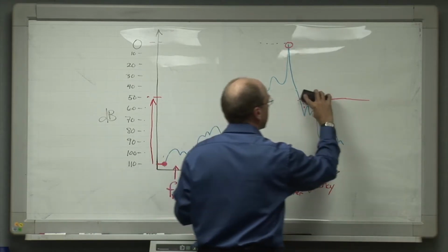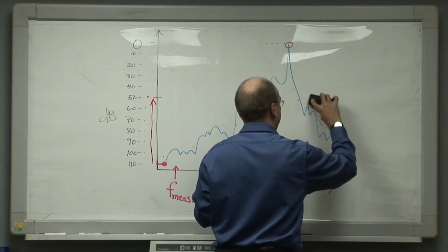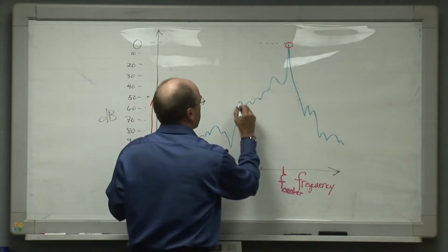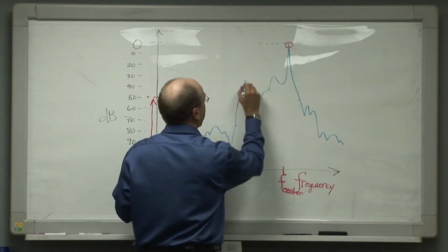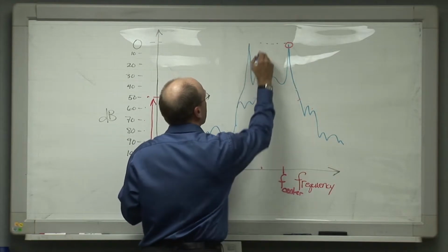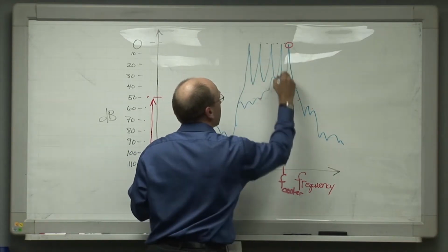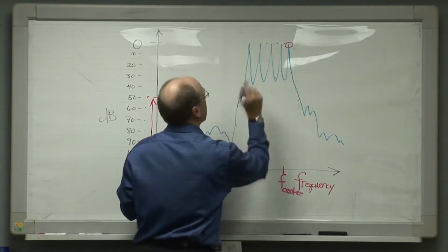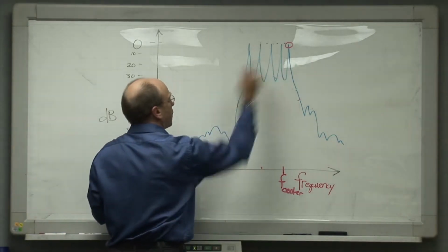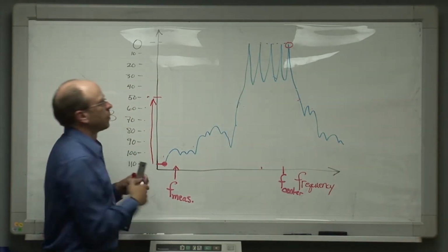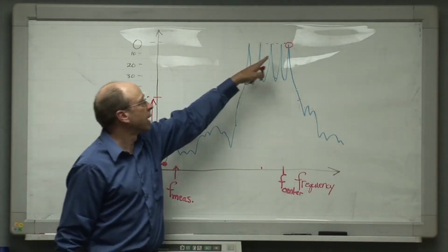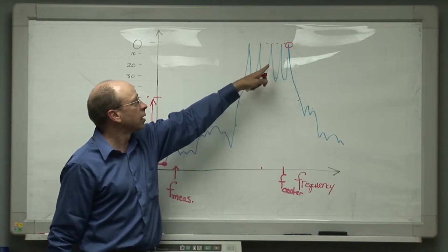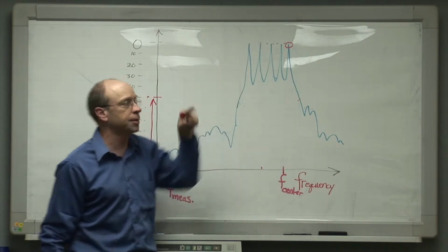do not transmit on a single frequency, but rather, and this goes back to the talk that we had about radar system design, radars nowadays typically have emissions which will look like this. And then I'm going to erase this part. And here, they will have several available operational frequencies. And as we talked about in the discussion on radar system design, they do this both to mitigate effects of interference and also to mitigate poor propagation characteristics on particular frequencies.